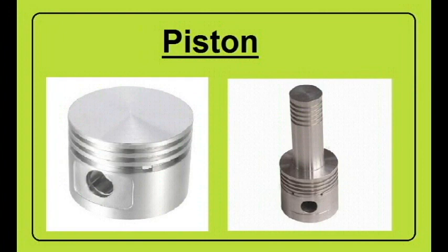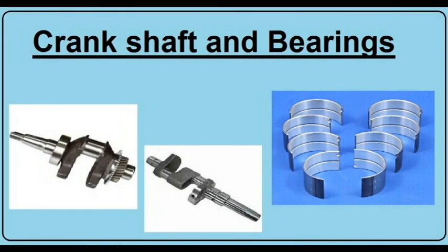Piston. Trunk-type piston is used in single-acting compressor. Tandem piston is used in multi-stage compact design. Aluminum alloy material is used for good friction properties and high strength with low coefficient of thermal expansion. Generally, piston ring material is alloyed cast iron. Crankshaft is usually made of forged carbon steel integral with counterweight. Cast steel, being prone to fatigue, is not used. Bearings. Thin shell type is commonly used in modern compressors and requires lube oil pressure above 2 bar.